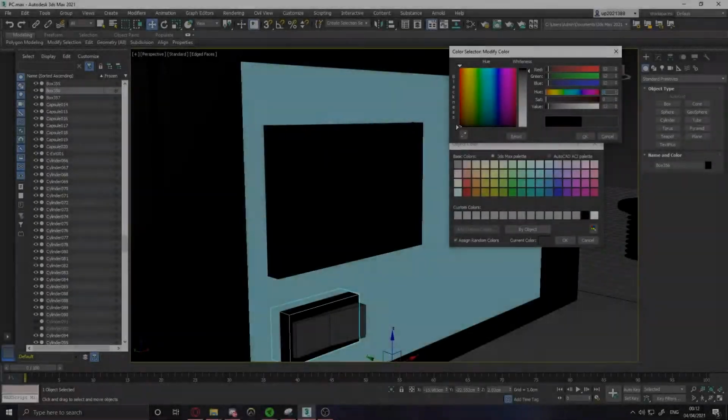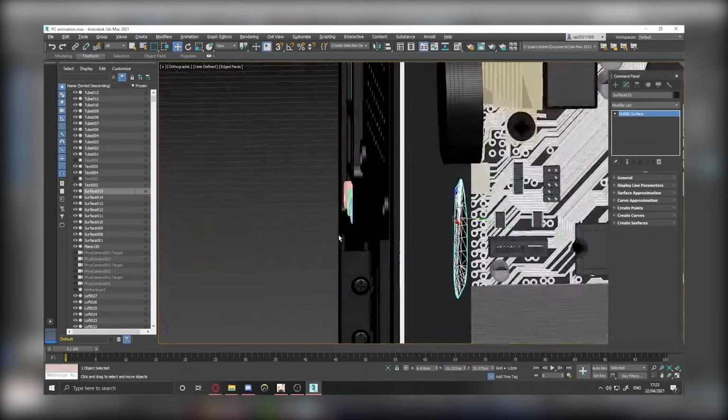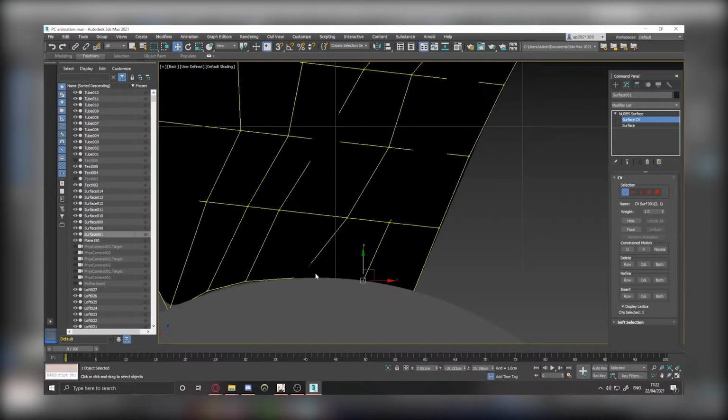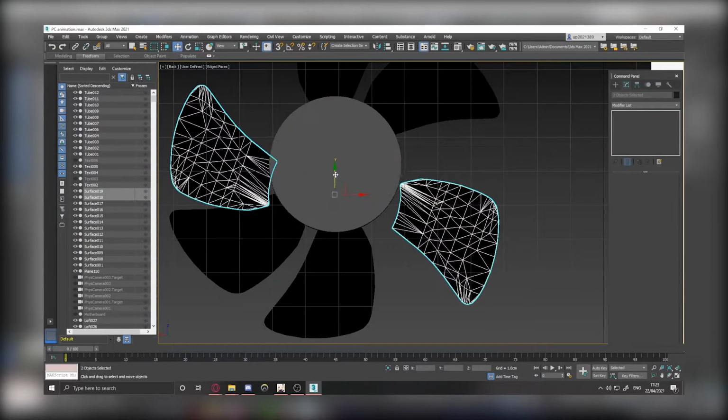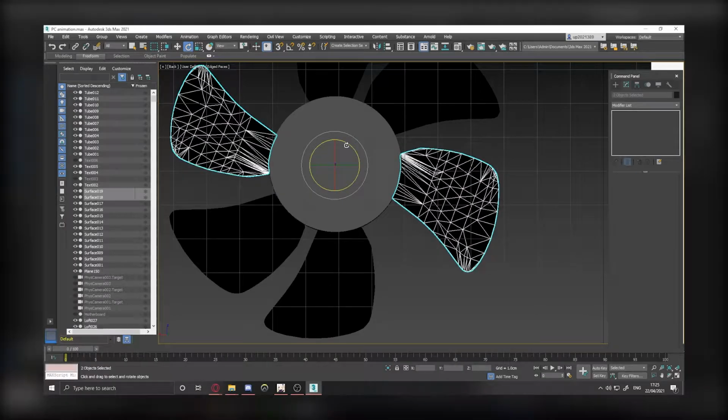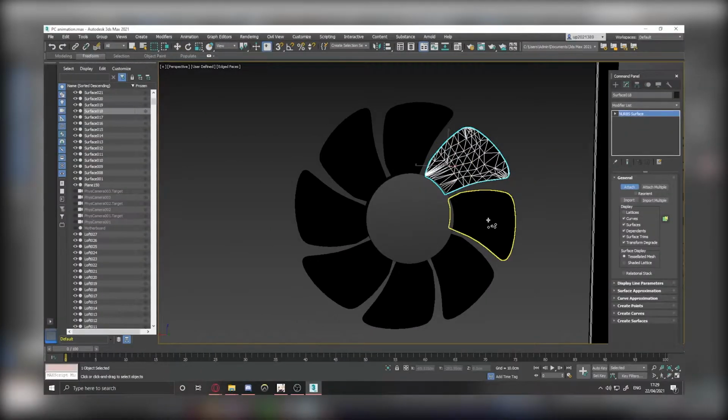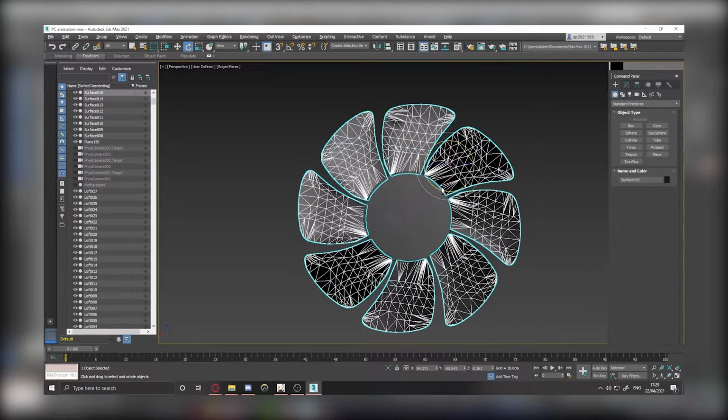To resolve this issue, I had to delete all the blades but one and readjust the NURBS vertexes so that it lined up with the base correctly. I then replicated the fan blades and made sure to take care when positioning them around the base of the fan. The next step was to connect them together using a union boolean.